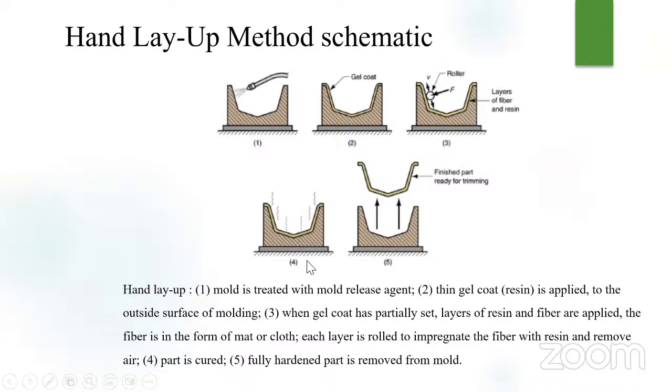See, in some cases it is being added, but in most of the cases, a one component system is being used. In one component system, you have epoxy or resin and hardener mixed together, so it will be cured only when you apply a specific temperature. That comes under compression molding, where you are giving heat, maybe SMC sheet molded composite.